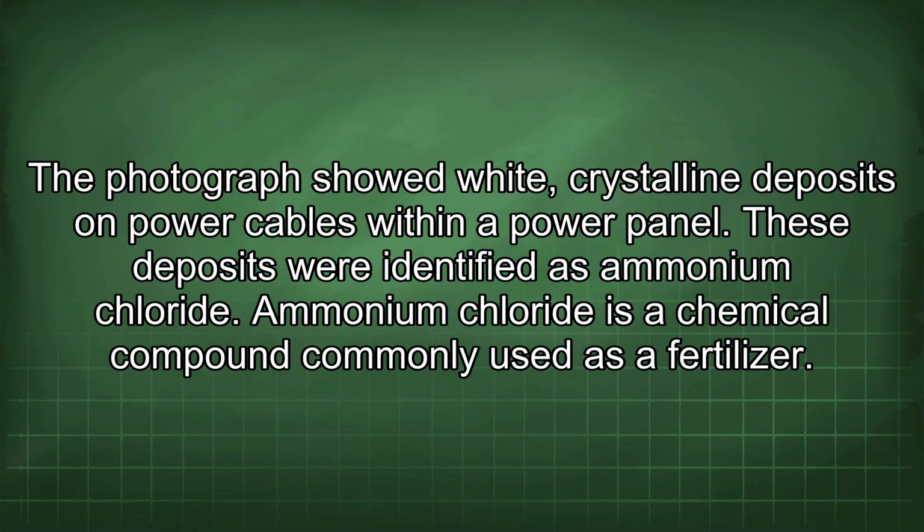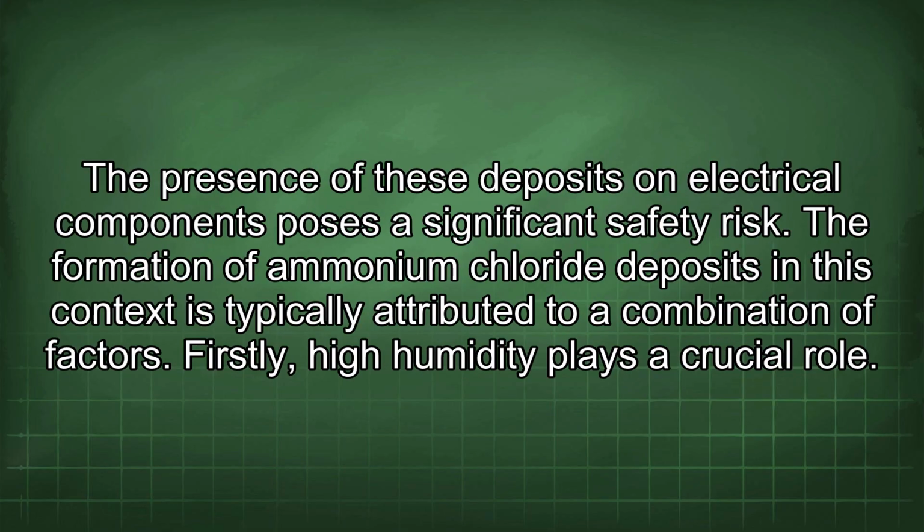A photograph showed white, crystalline deposits on power cables within a power panel. These deposits were identified as ammonium chloride. Ammonium chloride is a chemical compound commonly used as a fertilizer. The presence of these deposits on electrical components poses a significant safety risk.